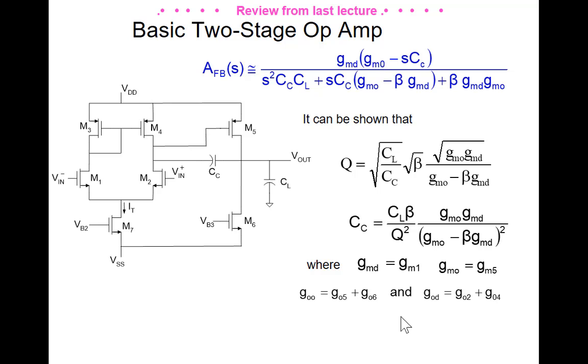Any two-stage amplifier with a tail current bias first stage, a tail voltage bias second stage, and a current mirror connected counterpart circuit. So if I were to have a telescopic cascode structure here, for example, that's one of the problems in the homework assignment I posted this morning. How would this expression here on the upper right change?